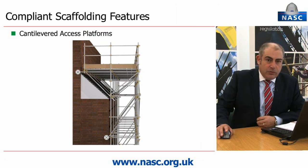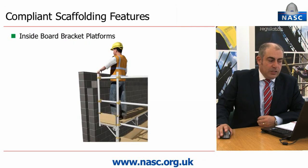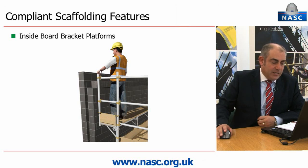Cantilevered access platforms to the inside face of independent scaffolds. The use of inside board brackets, or as they're commonly referred to, hop-up brackets, up to 500 millimetres above or below the working platform.